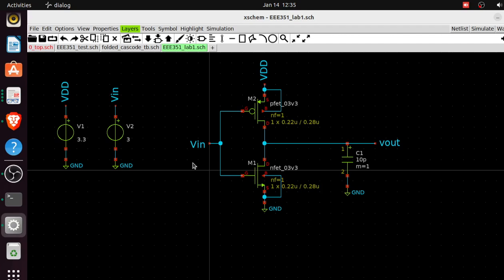Because if I was not doing these schematic captures here, like picking components, dropping them, wiring them, I could as well write a program for this using Spice. Usually that thing that looks like a program for this whole thing is called the Spice netlist. Don't worry, we're going to generate a Spice netlist for this, then you get to see what I'm talking about, that it looks like I'm writing a program.